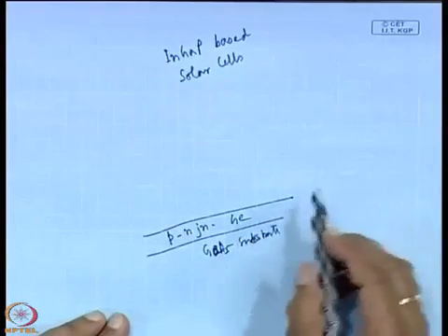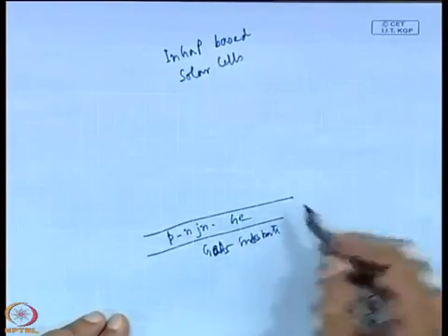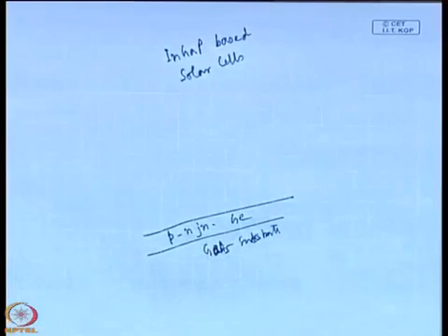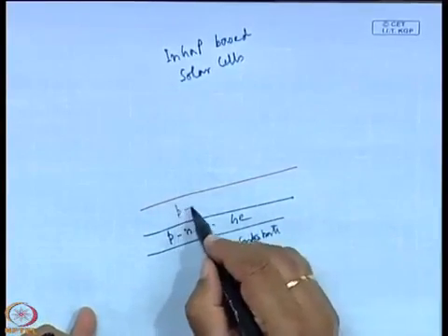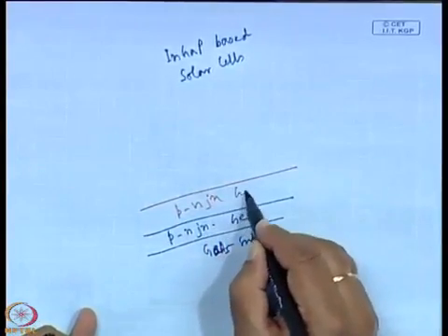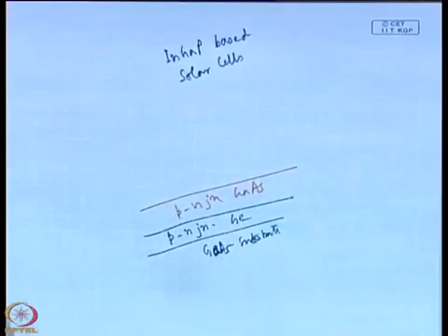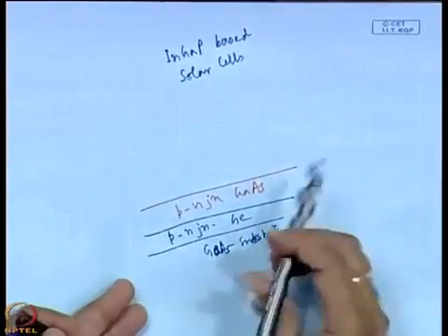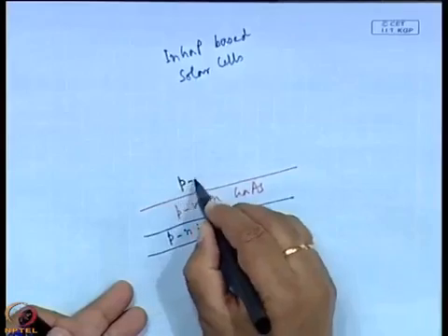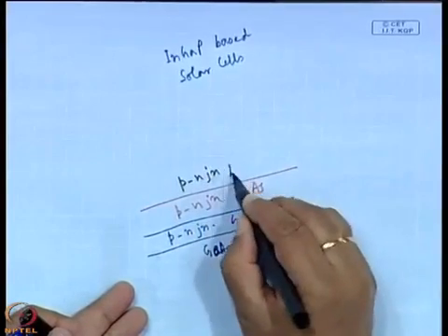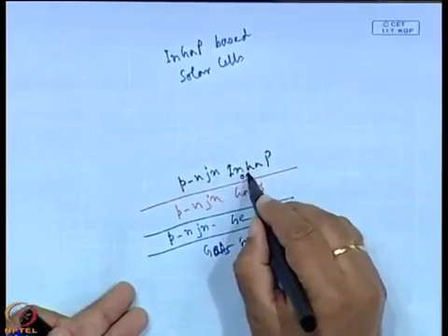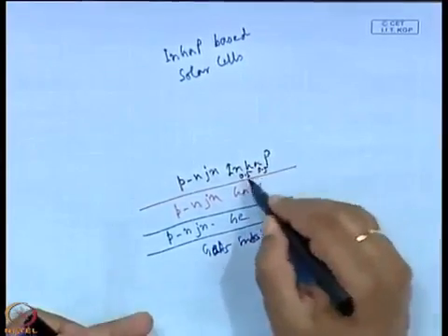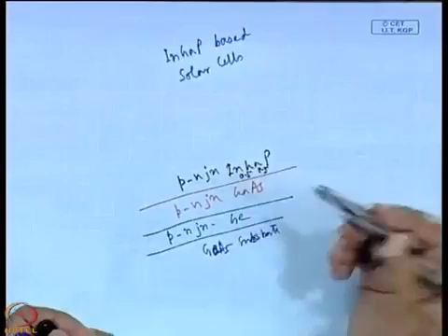So, very easily you can grow, free from any defect, the p-n junction of germanium. Then above it, you grow the p-n junction of gallium arsenide, and finally above that you grow a p-n junction of indium gallium phosphide with indium 0.5 and gallium 0.5; actually indium is 0.49 and gallium is 0.51.